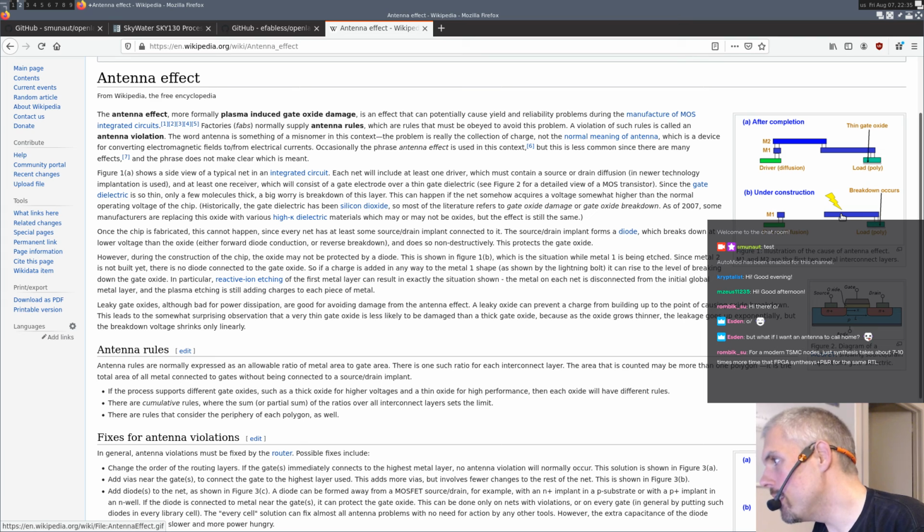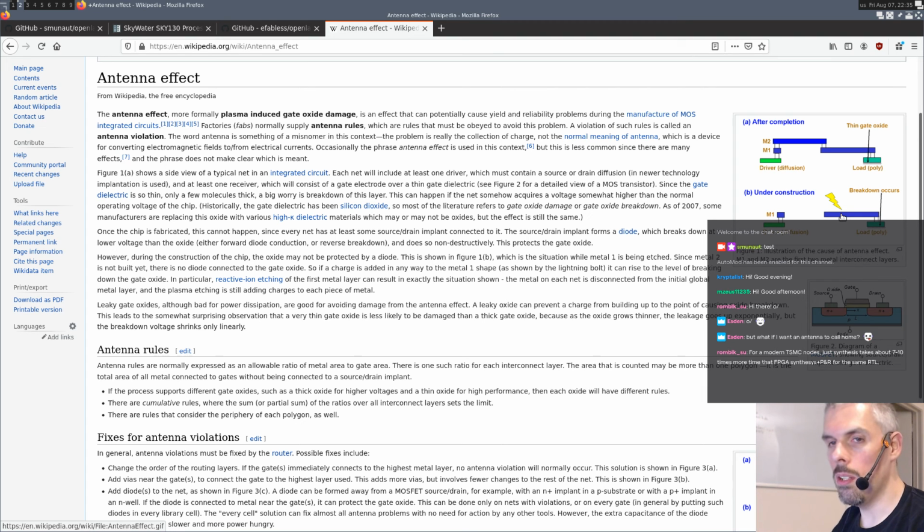Wow, yeah, the synthesis takes 10 times. Yeah, that's really not surprising. I mean, especially if you want good mapping to your gate library. I think the options that are given to users, even with the flow that we have here, are more optimized toward time than really good results.